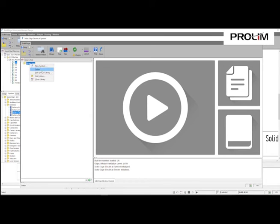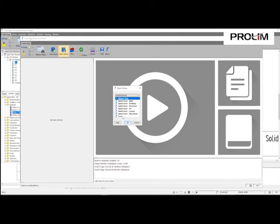And again, you can delete the libraries, you can edit the symbol library, so you can reconfigure it, you can edit the folders, you can change the names, and then you can just close the library. So all very simple stuff. So I've created this new library, and now if I close it and go back into open libraries, now I've got this test library. So now I can just start pulling directly from that. I can even create that as my default, so every time I hit open library, it just goes ahead and opens up that library test.